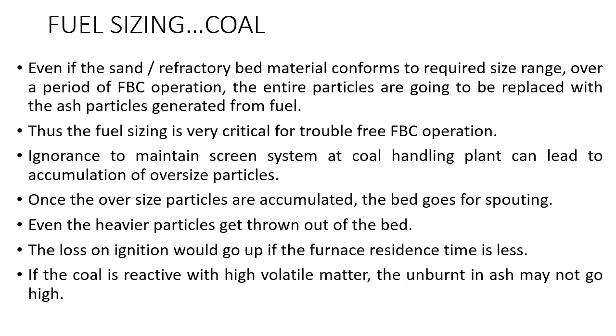Even the heavier particles get thrown out of the bed. The loss of ignition would go up if the furnace residence time is less. If the coal is reactive with high volatile matter, the unburnt in ash may not go high.